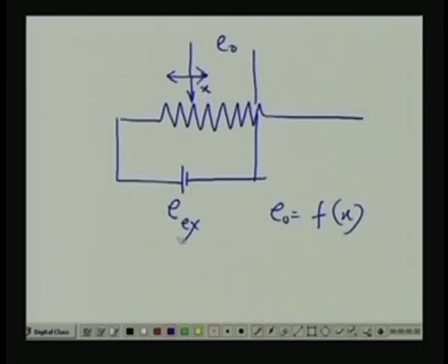its resolution. The resolution of an LVDT is extremely good. Please note, good resolution means its numerical value will be less. And another thing is, you will find that sensitivity in both cases I can change. I can change the excitation voltage Ex; if I change the excitation voltage, my output will also increase, or I can modify the sensitivity. I am not talking about this. I am talking about the resolution.